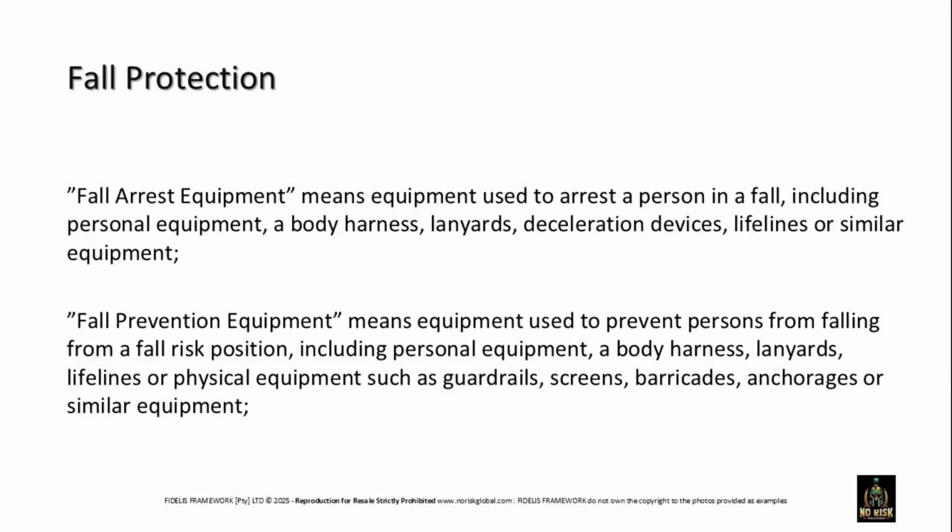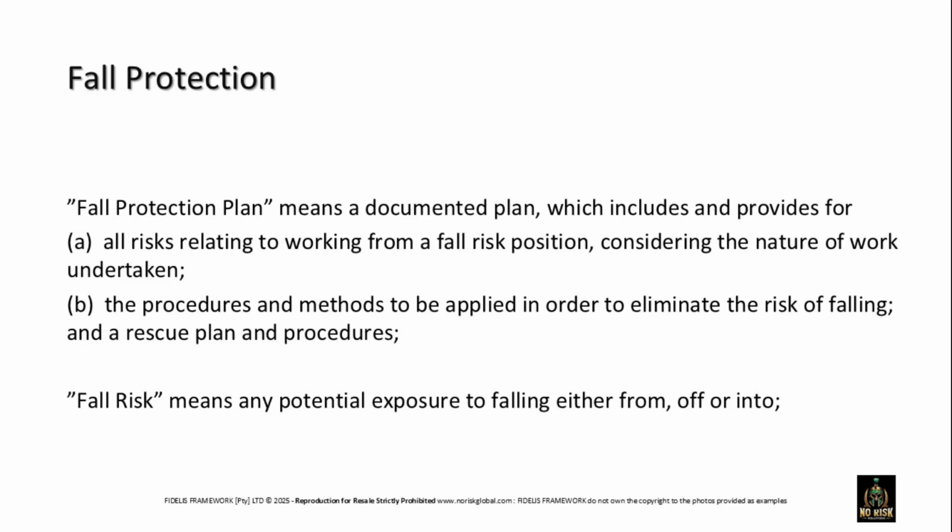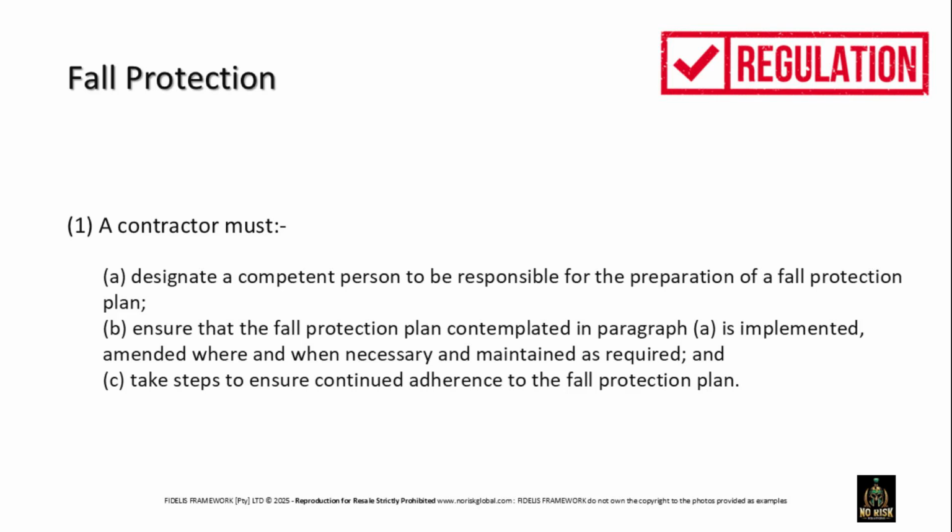Fall arrest and prevention equipment are essential for protecting workers from falls during construction. A fall protection plan must address risks and procedures to prevent falls, ensuring worker safety. To ensure safety in construction, a contractor must appoint a competent person to prepare a fall protection plan. This plan should be implemented, amended when necessary, and maintained to ensure ongoing adherence.